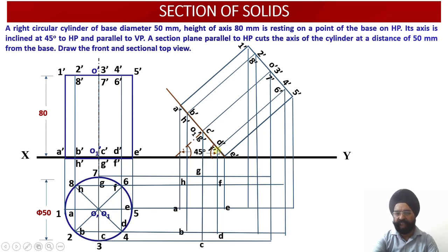Similarly, you draw the vertical projector through D dash and F dash. Now work out the horizontal points of intersection through D and through F. Again, another two points have been located. And finally, draw the vertical projector through E dash. Wherever it meets the horizontal projector through point E, which is the plan projection point in the previous view, you get the location of point E over here. Similarly, these points have been worked out.